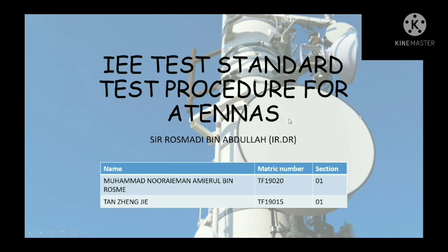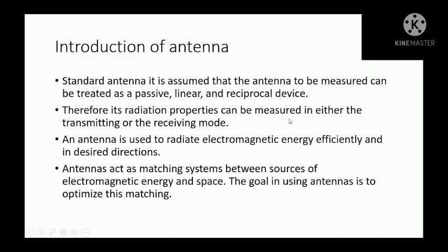Procedure for antennas. For the introduction of antennas, standard antenna is assumed that the antenna to be measured can be treated as a passive, linear, and reciprocal device. Therefore, its radiation properties can be measured in either the transmitting or the receive mode.